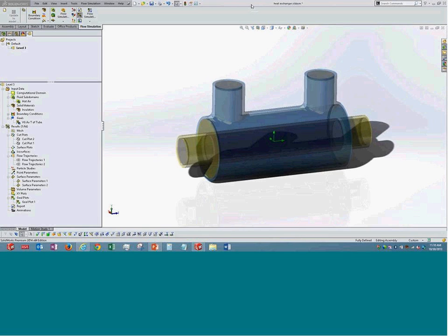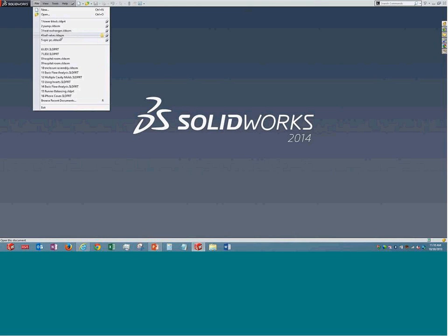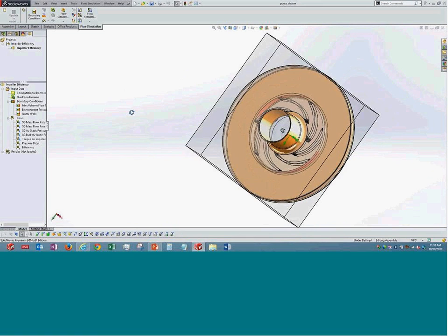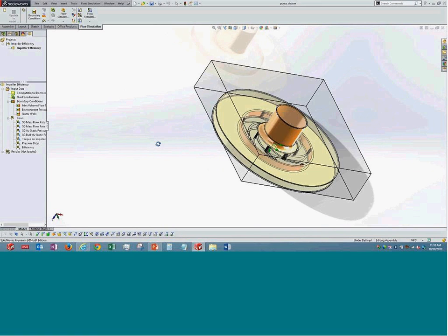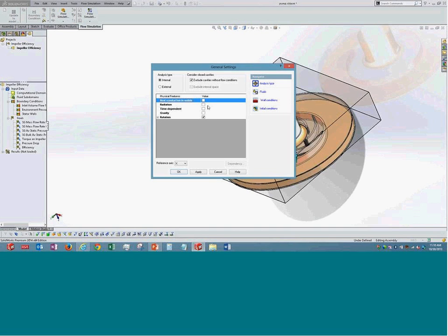Now, if the entire system is assumed to be rotating, the simulation work is a bit different, in the sense that it uses a kind of relative motion. If a fan is rotating in practicality, in simulation we are not rotating the fan, but we are rotating the air around it.